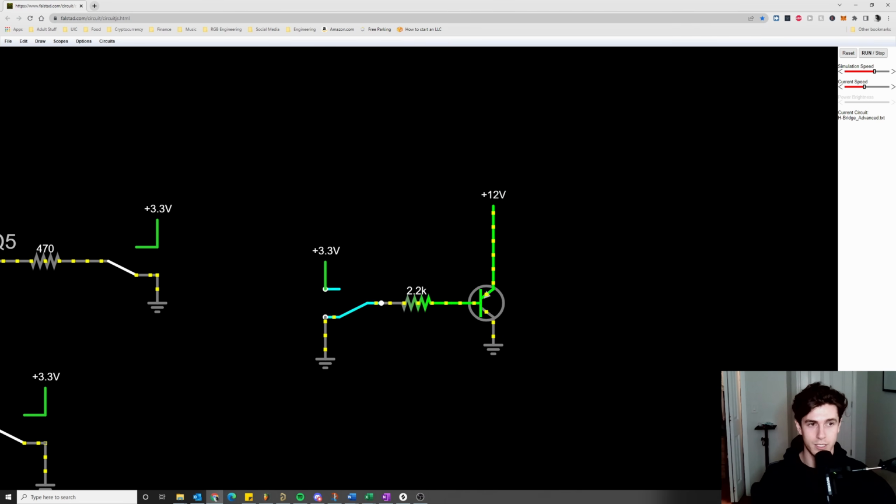And by looking at the rest of the circuit here, maybe you already see where I'm going with this. So let's say we're trying to control a PNP transistor with the GPIO pin of a microcontroller, where the maximum output voltage is typically about 3.3 volts. So with a microcontroller, your options are 3.3 volts or 0 volts, right? Which is why I have this switch here toggling between 3.3 and ground.